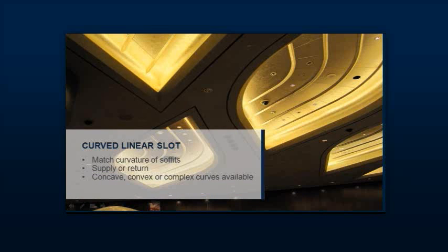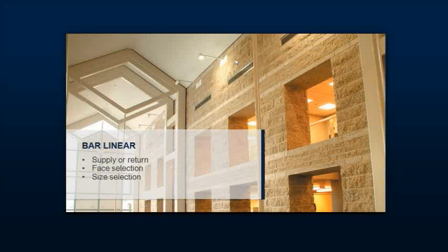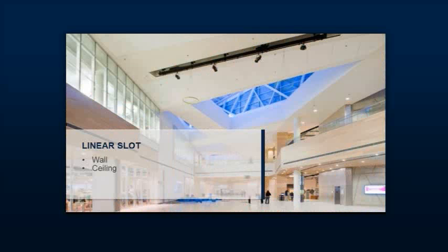What's the degree? Well, first off, there's several levels to mock-ups. One of the most common requests doesn't actually involve much on your side. It's: will this shape perform correctly? We call that a laboratory mock-up, performance related indices, and we do those a lot for displacement in particular because it's more commonly customized, and actually increasingly for chilled beams as well.